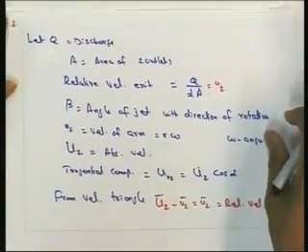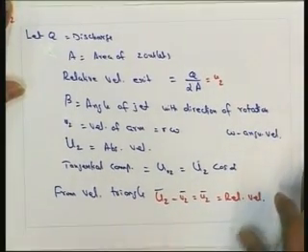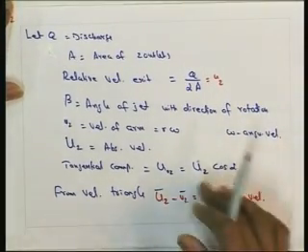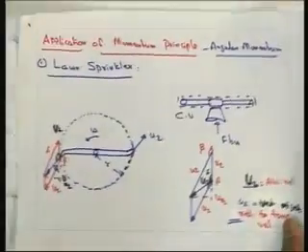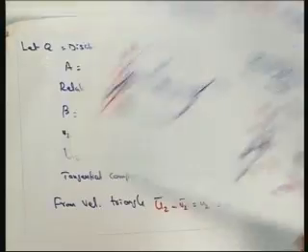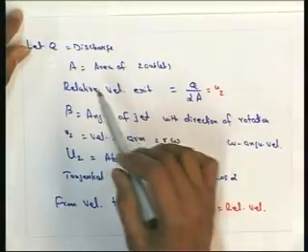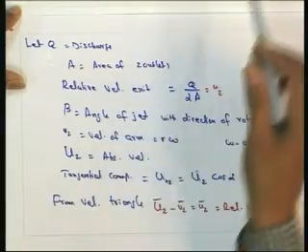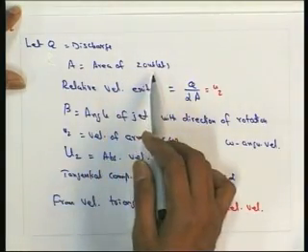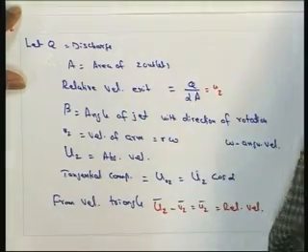With respect to this we will further explain how we can find out the various parameters like the torque, or how, if one parameter is given, to determine the other parameter. So for this particular system, let Q be the discharge coming through the pipe. So that Q is divided into two nozzles. If A is the area of the two outlets, the relative velocity at exit will be Q by 2A.